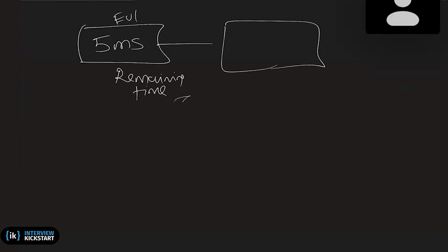The timer is already in progress with 100 millisecond tick count. And then next 10 millisecond came in, and then next 5 millisecond came in. So 100 is the one which is already in the pipeline. I mean, it's already decrementing. The timer is decrementing. So what happens to the 100 millisecond one if 10 millisecond comes in? Yeah. So basically, let's say it has decremented to say 95 or 98. 2 ticks have expired, right? I'm assuming every millisecond you are getting a tick.